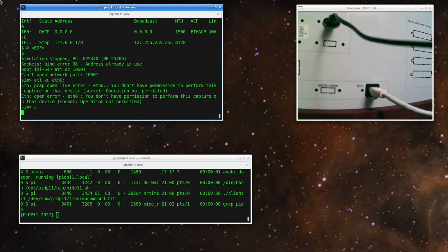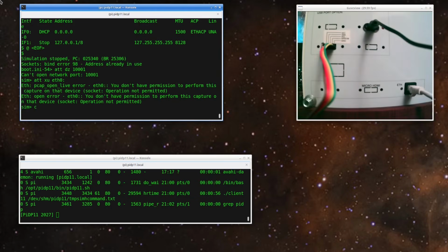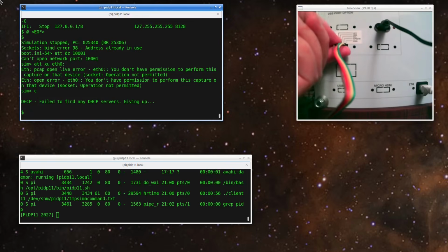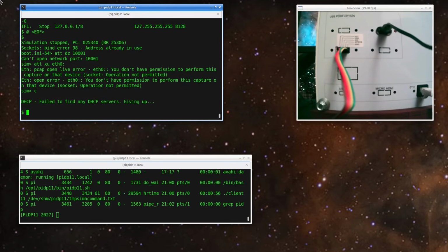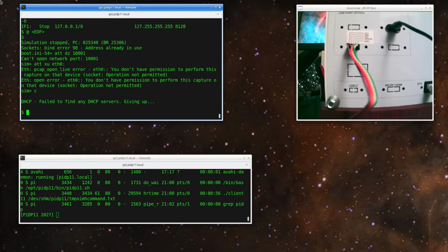Power port up here, and then I took the I2C wires, power and ground, and the one unused GPIO 19, and I farmed that out through just a set of points where I can put wires into, or a connector.